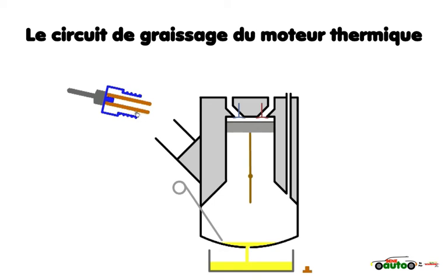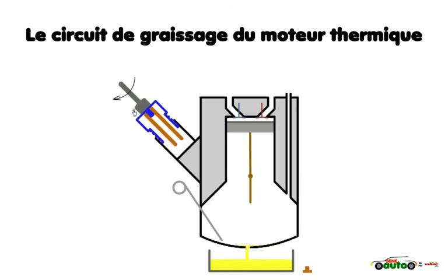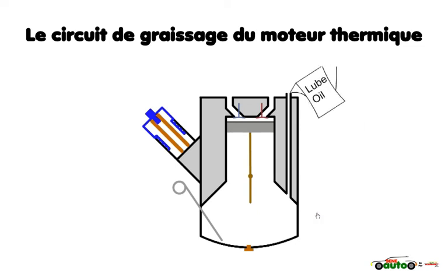The element contains no metal parts, it's manufactured from paper and plastics, and is suitable for incineration, capturing heat from the waste oil. The new filter and O-rings are fitted and the housing is tightened to the correct torque. Dispose of the old oil in an environmentally friendly manner and tighten the drain plug.